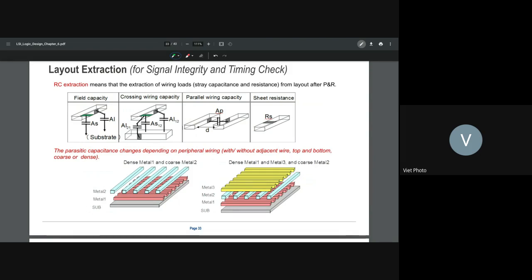You have this one. You see that this one is the width, the metal Y, right? Those metal Y here. So these two are perpendicular. Let's say metal 2 here, then metal 3 will be like that, and metal 4 will be this, and metal 5. I just put different colors so that you can see. Now here's the metal 4. So the even layers will be horizontal and the odd layers will be vertical. And now metal 4 is like this, and so on.